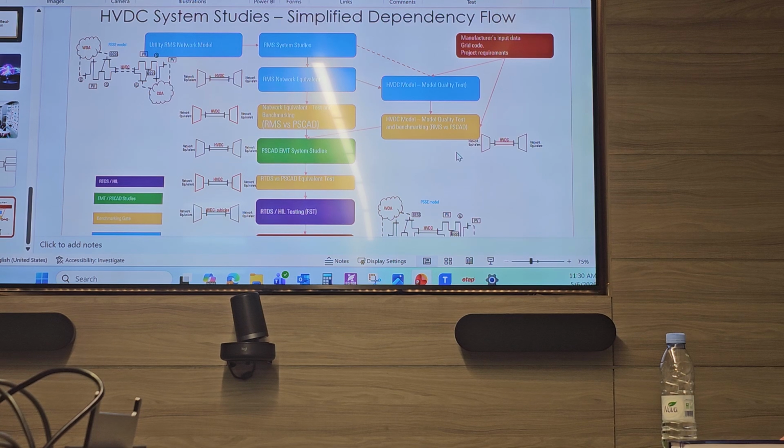So what you simulate in PSSE, you simulate here. You simulate short circuit, and the short circuit current should match. For the dynamic model, you simulate a fault, clear the fault, and watch frequency and voltage, and you will get some curves. The same in PSCAD. So the target is that these two must match. Why is that important? Once you reach this point, that will make sure that here is your network equivalent, also benchmarking, and PSCAD goes in parallel.